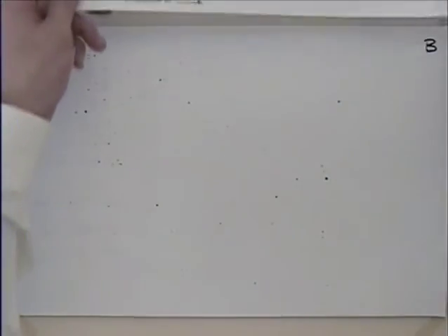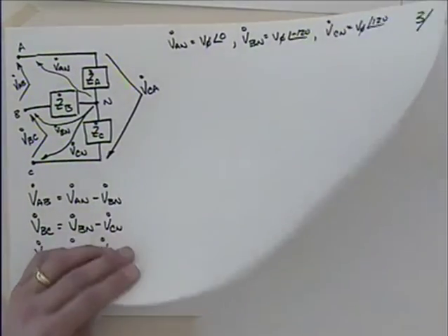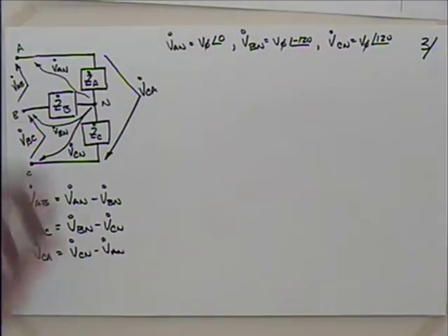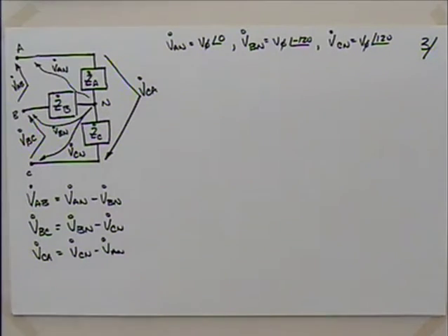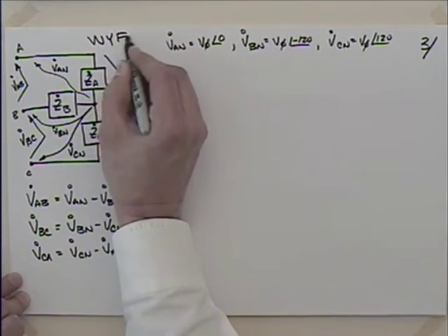Okay. Well, so how did we get on that first Y? How did we get from 120 volts to 208 volts and whatnot? That's what I would like to address with this. And we could analyze this for a source if we wanted to. I'm going to analyze it as a load, so I come up with a Y load. So this is a Y.